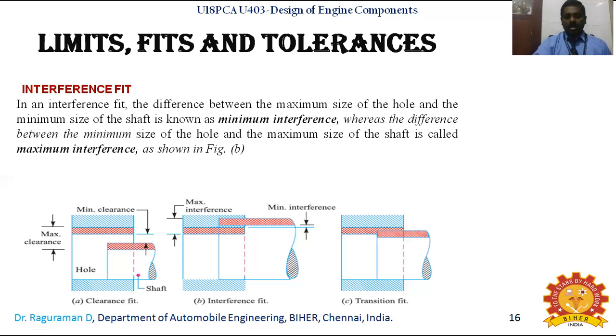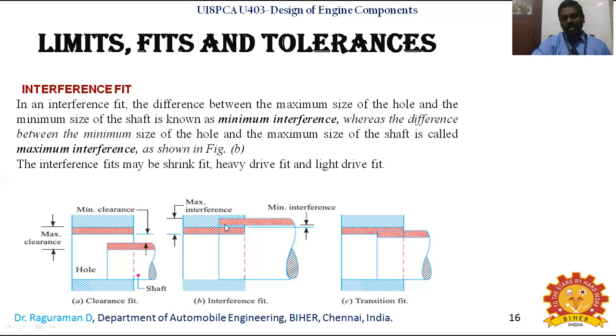So here you are required to give a press fit. That's what you will be saying a shrink fit, heavy drive fit, light drive fit. Otherwise, it can also be said as a press fit because you are required to give tons of loads to make a fitting. So that's why you will be making other names: shrink fit, heavy drive fit, light drive fit, and sometimes press fit also.